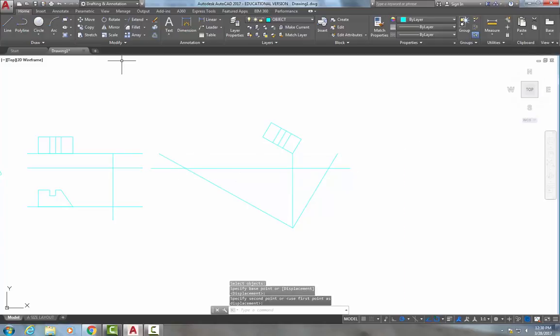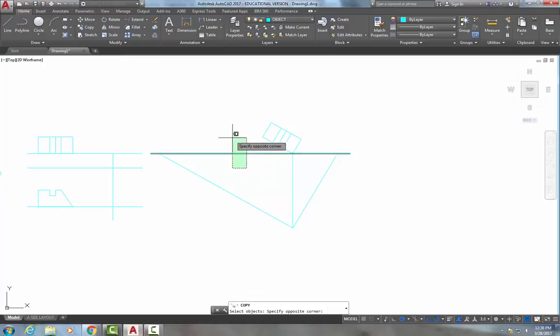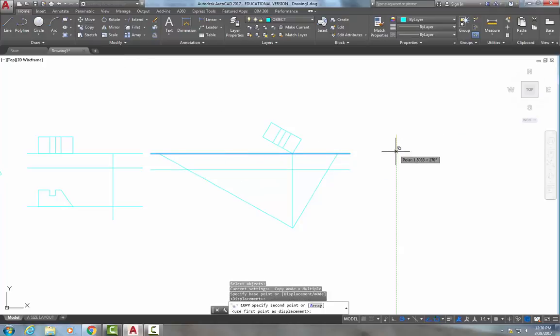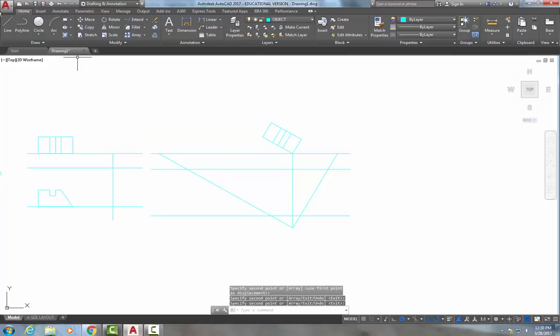It does not have to, let me back up, I want to copy that. It does not have to line up with the horizon line that I did in my 1 point. I just think that's about a good place. And then I'm going to put my ground line down here. Remember, no matter where the horizon line is, we drop vertical lines from where our angled lines hit our picture plane line down until it hits our horizon line. So just like that, I've got my vanishing point left and right.